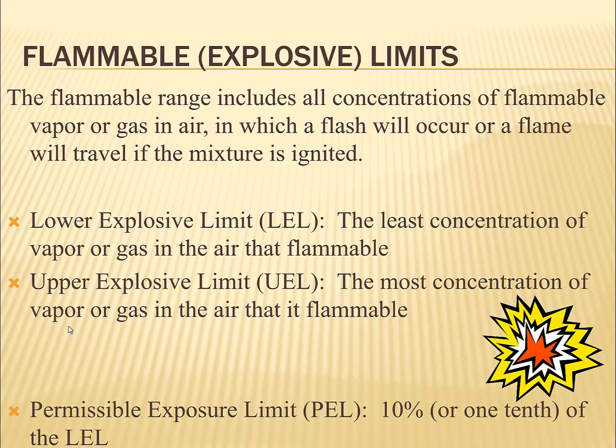However, there's another term, it's almost the same. It's called the lower flammable limit, LFL. And that means the same thing, so you can see it either way. And then, if you get too much, you can get to a point where there's so much vapor in the air that it can't ignite anymore, and we call that the upper explosive limit, or the upper flammable limit, the UEL or the UFL, either way. Sounds like a football league or an alien spacecraft.